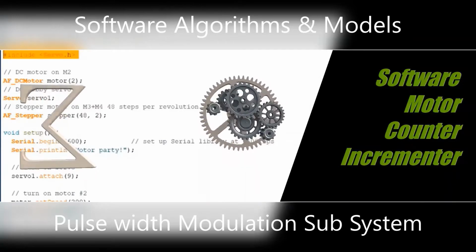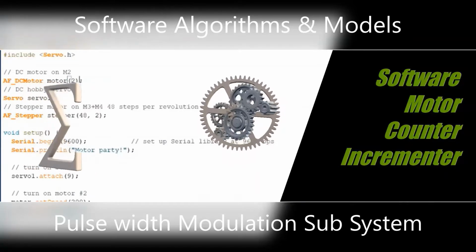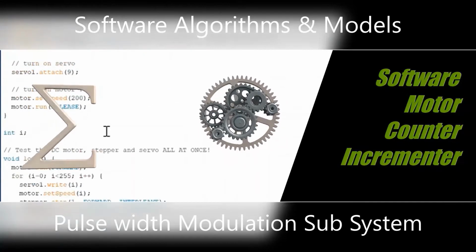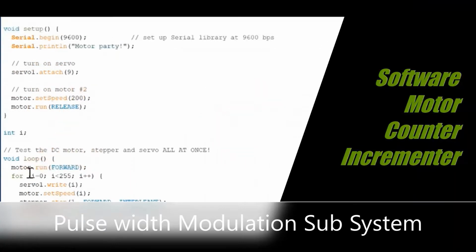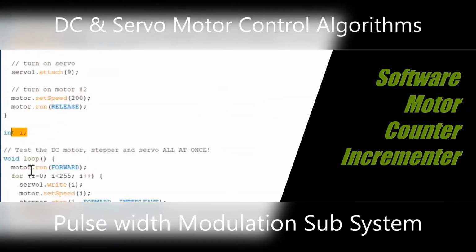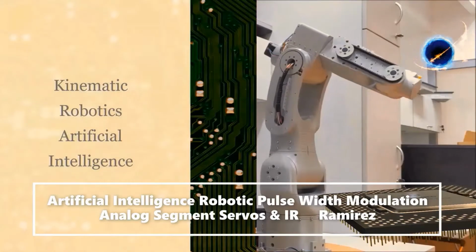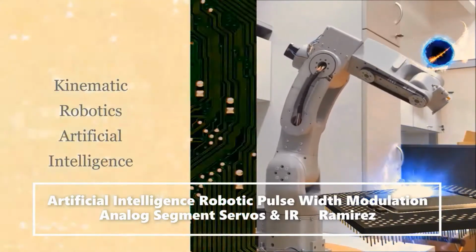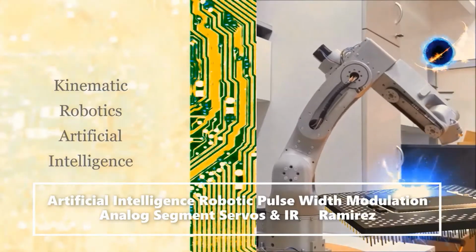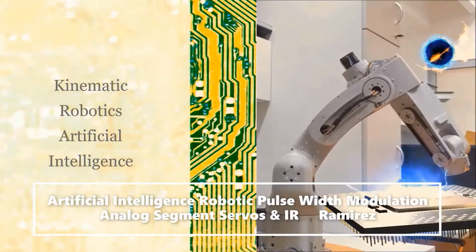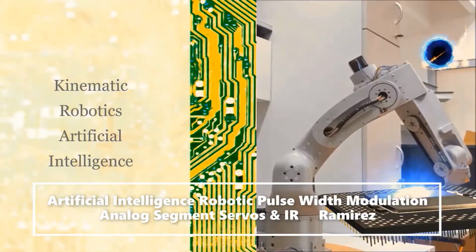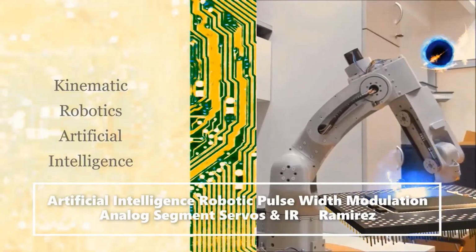The DC motor software constructor takes no arguments. The motor object is typically initialized by assigning the motor object retrieved from the pulse width modulation shield. So create the motor shield object with the default I2C address.